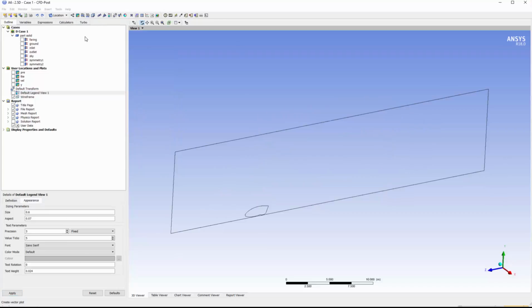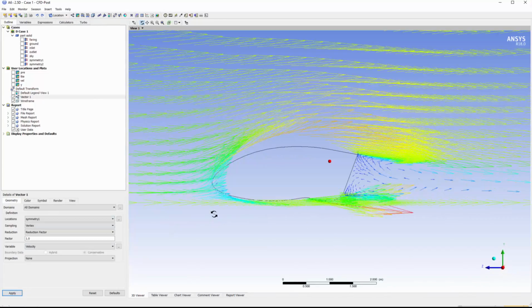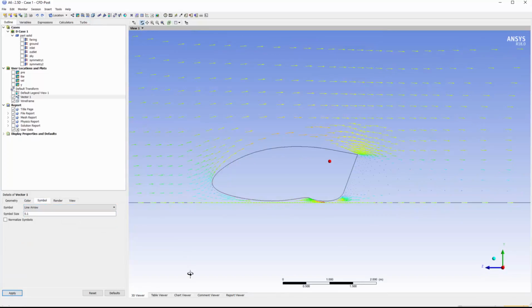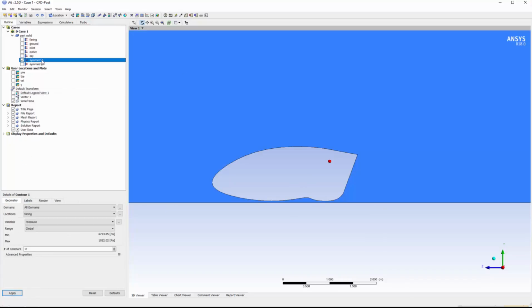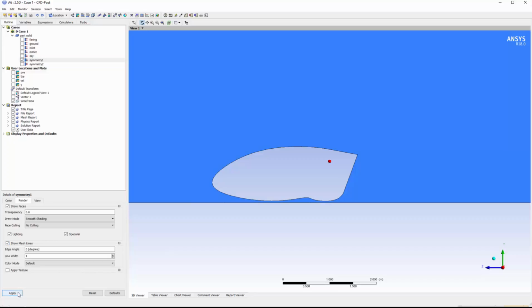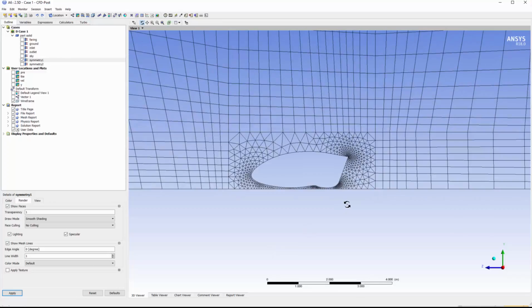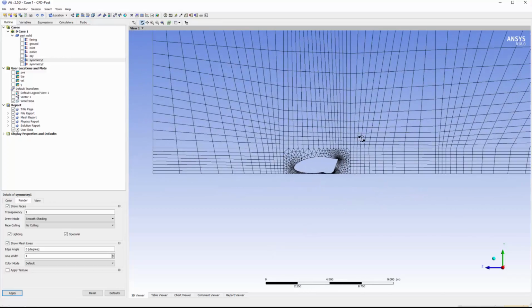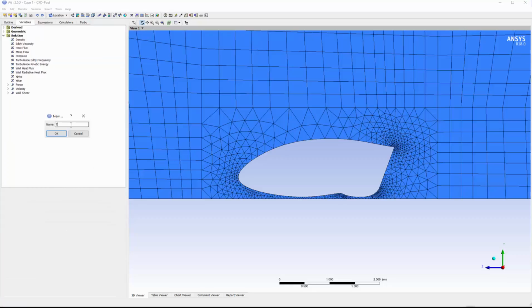After setting up the contours, we can show the velocity vectors on each cell of the symmetry plane, changing the scale if needed. We can use this as another check to ensure velocity direction and magnitude of the walls are correct. The turbulent viscosity ratio is the ratio between the turbulent and laminar viscosity. By plotting this against the symmetry plane, we can see the transition of the boundary layer from the laminar sublayer to the turbulent log region.